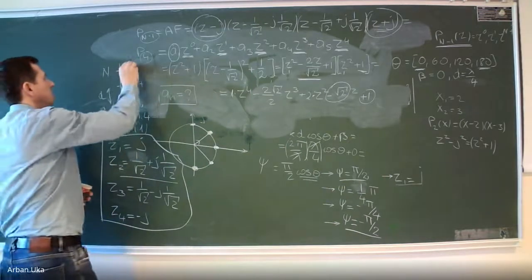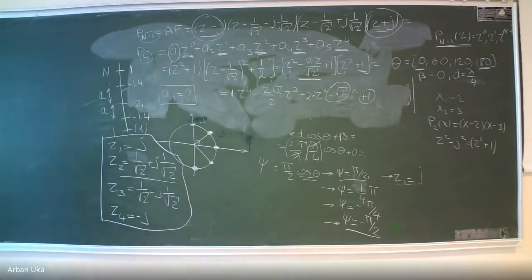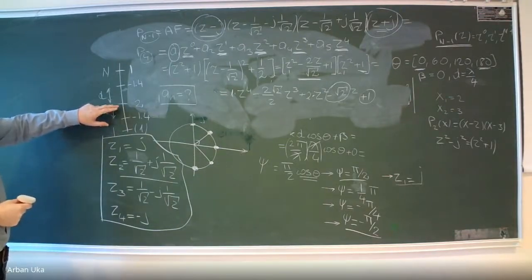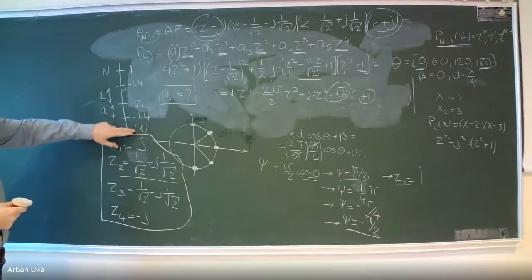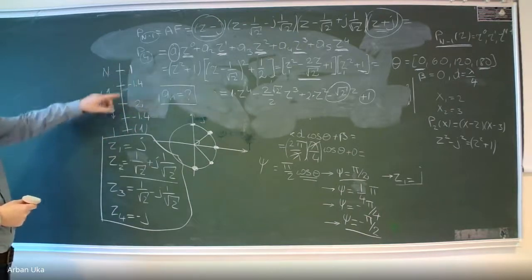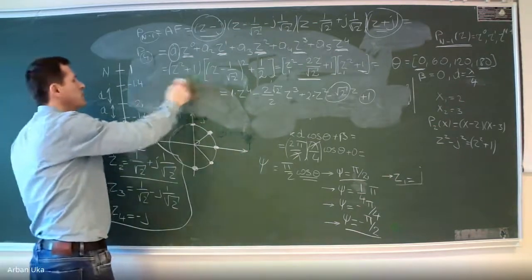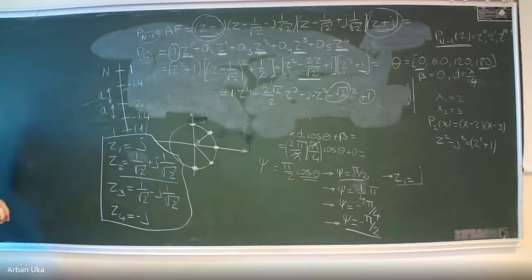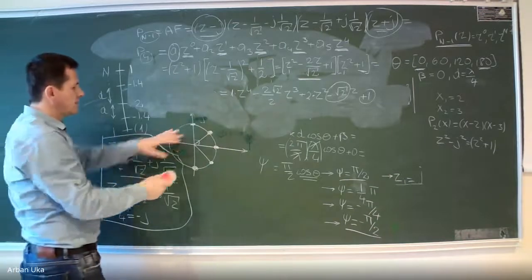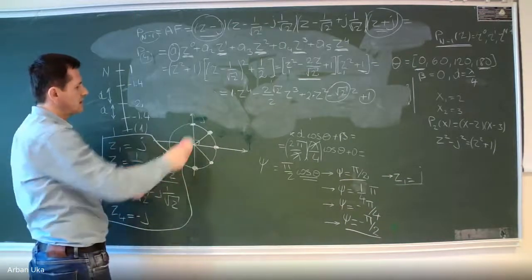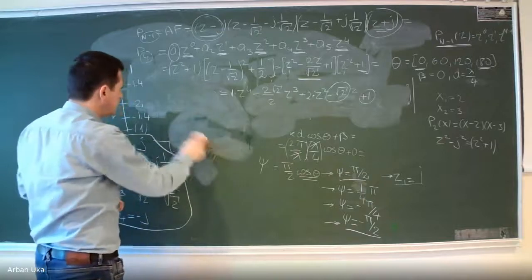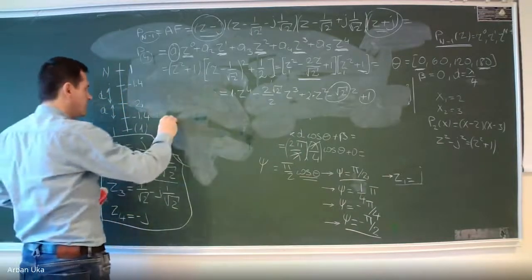Okay. So for this antenna, even the excitation coefficients are to some degree symmetric, right? The center antenna element has an excitation amplitude twice that of the ones at the edges, and here we get minus 1.4. But when we have this minus 1.4, we can also think about it in this way. Let's erase this one. This was just to figure out what the z was as a function of the angle psi. We can also think about this one this way.